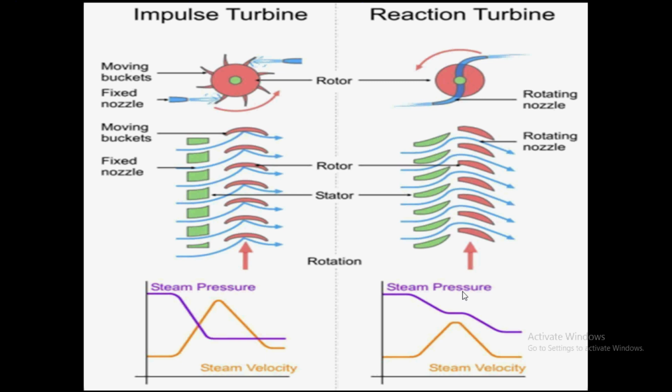Labyrinth seals consist of a series of thin strips fixed to the casing or other stationary member and arranged so as to maintain the smallest possible clearance with the shaft. The labyrinth seals have small restrictions that increase the velocity of fluid leakage only to have it dissipated into the pockets, thereby throttling the fluid.